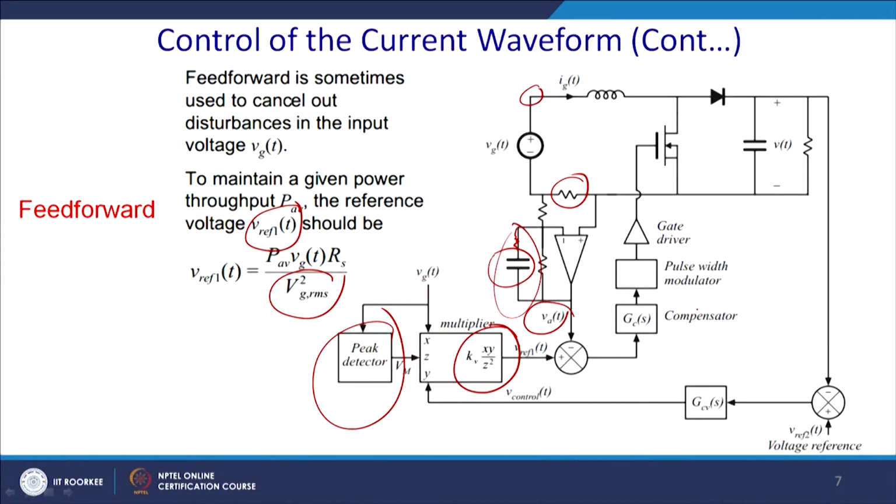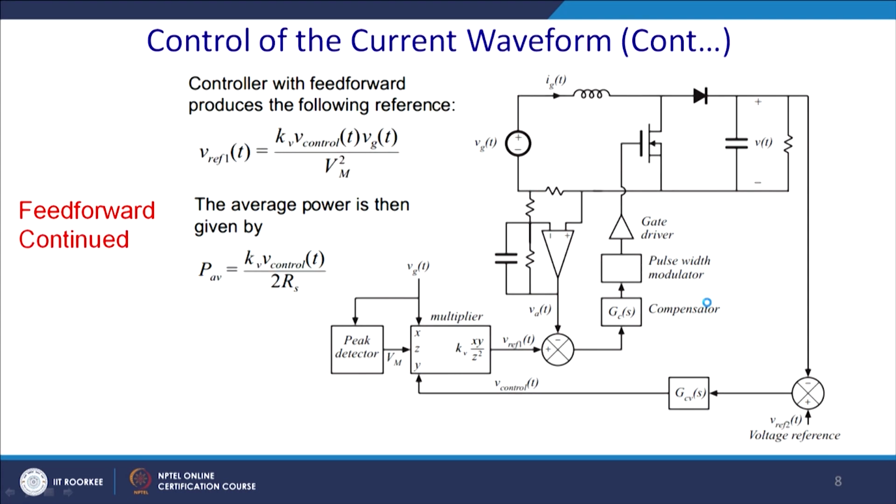So, you can do it in that way and calculate the actual values of RC, and this gives you the gain. So, how much scaling you require, and this sums up the effect, and thereafter you get a comparison, from there you get a compensator, which will give you the stability and the promptness. In the same way as I told you, there is a PWM and it will work. So, this is the overall control circuit of the boost type PWM rectifier.